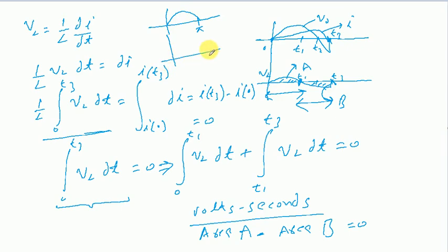Now here in the case of a resistive inductive load, we have something like this. There is some negative part of the voltage over here. So it is clear that if you compute the average or DC value of the voltage for an RL type of load, you will have an average value which will be lesser than in the case of a purely resistive load.